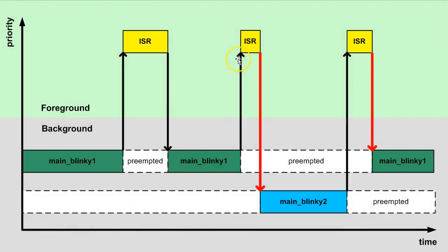First of all, you can see that such switching the CPU between executing multiple background loops should be possible. Second, the exercise points you to the general mechanism for such CPU context switching, which is to exploit the interrupt processing hardware already available in your processor. And third, the exercise illustrates the general idea of multitasking on a single CPU, which is to switch the CPU between executing different background loops, like your main Blinky1 and main Blinky2 here.